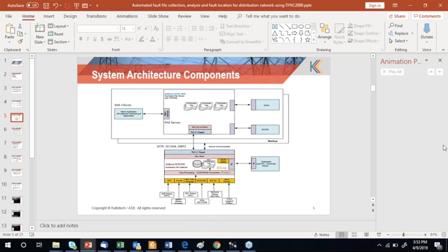Whenever we propose this, people prefer the newer 61850, so they get it automatically, but the other mapping is a bit tedious, because for every event there needs to be a description, and the values and other descriptions also need to be provided. So the answer is, for automatic collection we only have 61850. For other protocols, though we collect the data, mapping is needed to make it a user-understandable format.